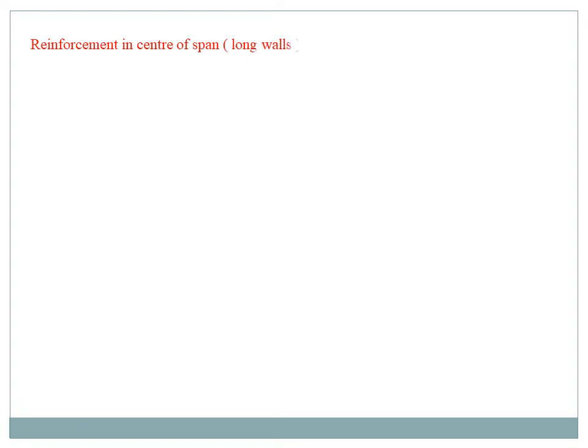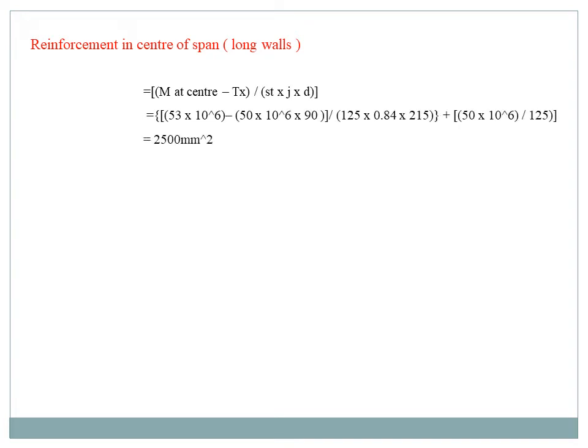Then reinforcement in center of span for long walls. For long walls reinforcement, the formula is moment at center minus Tx divided by sigma st into j into d.